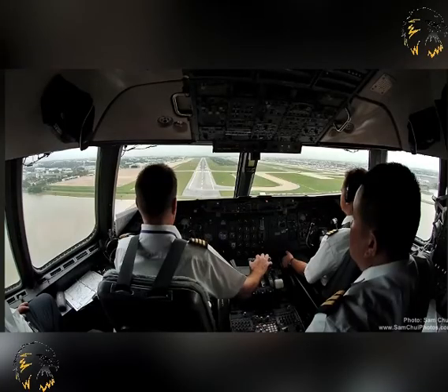Until standalone GNSS precision approaches are fully developed, a precision approach will probably mean an ILS approach, and in this instance the final approach segment begins at the FAP. You should recall that this is the point in space on the centerline of the localizer specified for the final approach track, where the intermediate approach altitude or height intersects the nominal glide path.